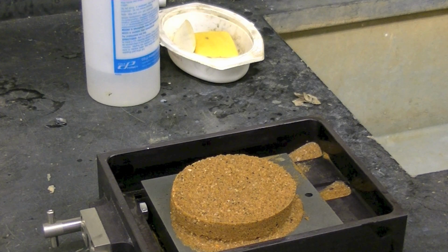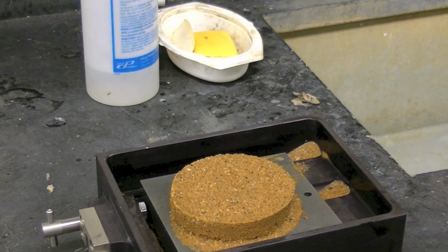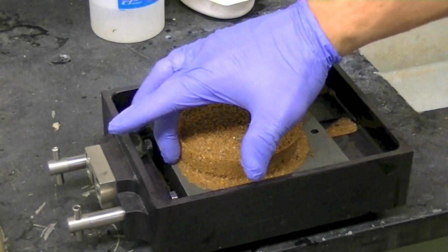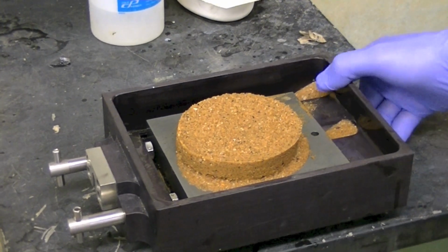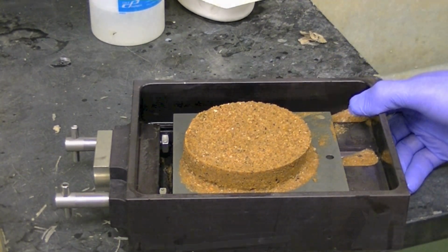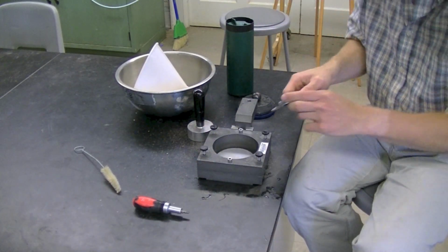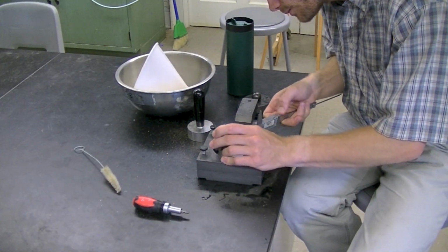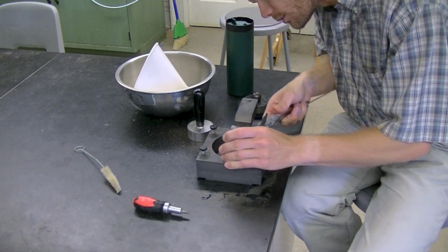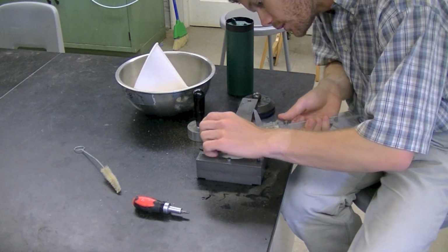After pouring out the water and removing the top half of the box, notice how the sample has shifted during the test. This is the direct shear effect. Do not forget to record the dimensions of the shear box. Measure the diameter of the shear box, for this will later be used in calculating the cross-sectional area of our specimen.